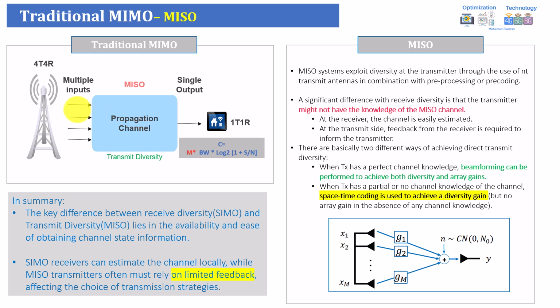The second one is that it will transmit at different times, or different time slots, for example. This will ensure, for example, that one of these data copies will be received faster by the receiver, which even improves things from the receiver side. So the antenna will receive the data four times, and it will just select the best one at the end, because it received four versions, so it will get the most out of them.